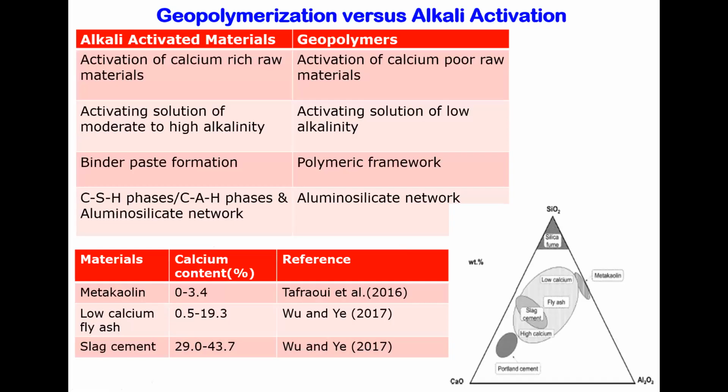There is also a fundamental question for most students and viewers: what is the fundamental difference between alkali activation and geopolymerization? If you look at any geopolymer presentation, this question comes to the picture, so I hope this slide will clear that doubt. Fundamentally, this is compiled from the literature. Alkali activation means activation of calcium-rich raw materials, while geopolymerization means activation of calcium-poor raw materials. Here it has also been given which are the calcium-rich and calcium-poor materials.